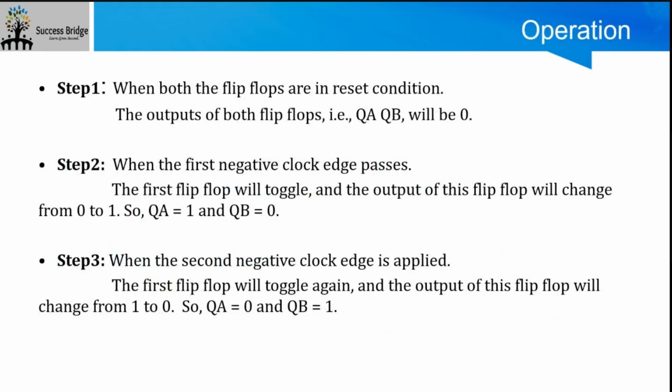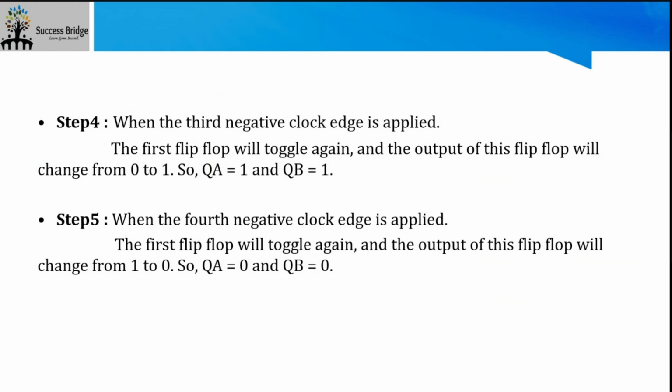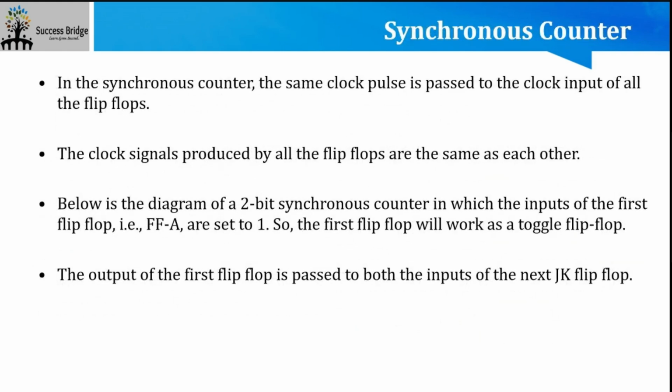Let's see synchronous counter. In real time, we always use synchronous counters because clocks have to be in a synchronous stage to allow the data to be synchronous. In the synchronous counter, the same clock pulse is passed to the clock input of all the flip-flops, and the clock signals produced by all the flip-flops are the same as each other.